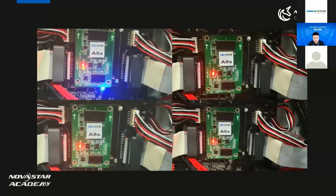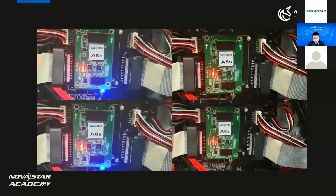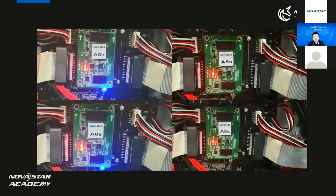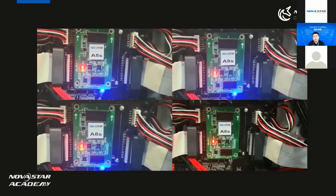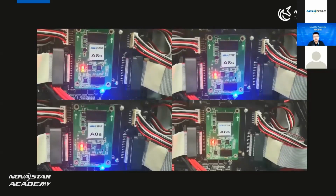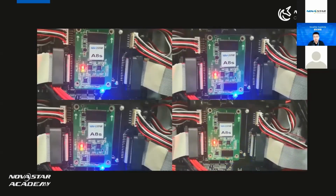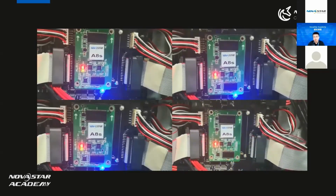And the top left corner, it is in backup mode because you can see it fast flashes 4 times and waits half second. How about this one? This is working normally because it flashes once per second. And this one is no video source connected. It fast flashes 3 times and waits half second. And then another 3 times, fast flashes 3 times.